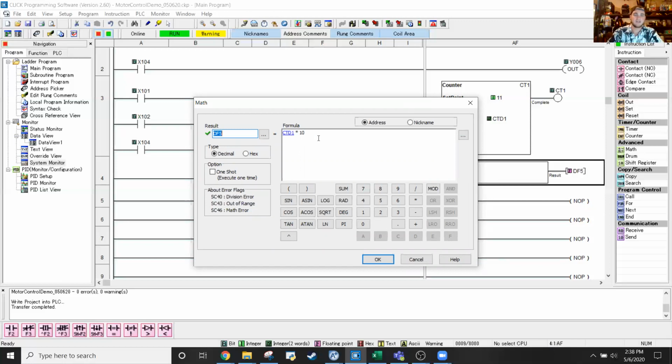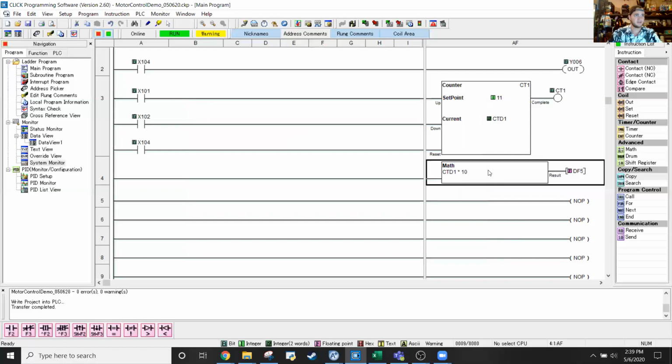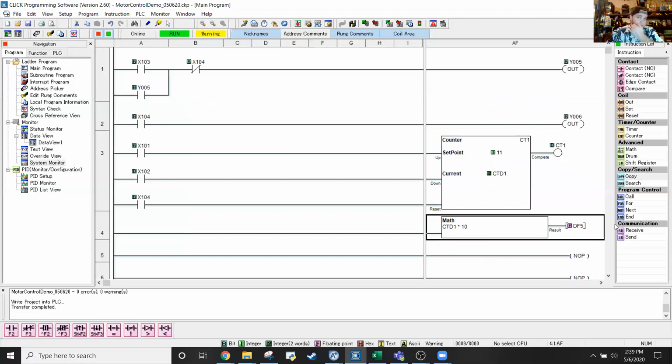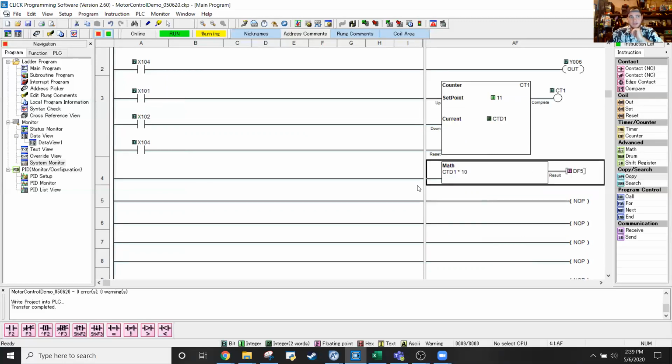Because what we could do is we could use this math block to do that scaling operation, write that new value into some point in memory, and then I could use a copy to copy that value from some point in memory and write it out. And it might make sense to do that in certain areas, but for us, this is a really simple program. This is the way we're going to do it, because it's easy and simple, and it's easier to follow. Okay. So this looks pretty good. I think this program will run as is.